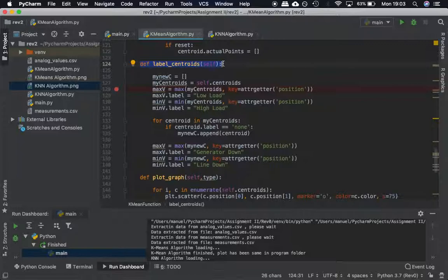Therefore it is expected that the value at the receiving point, which means at the load point, will be lower compared to the sending point, which means the generator. By the opposite, when the load is really low, the voltage is expected to increase, which means to be high.